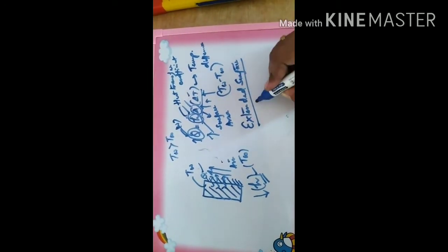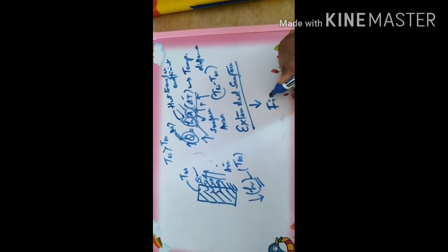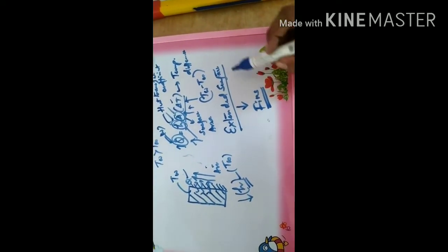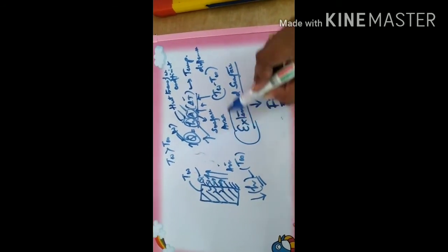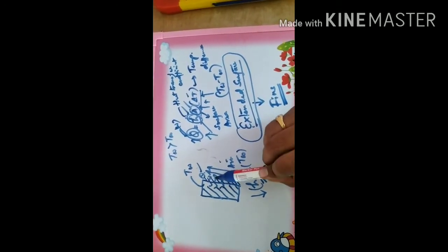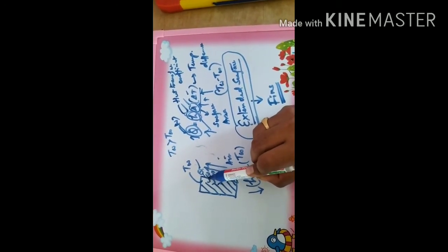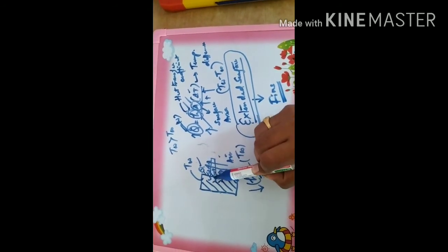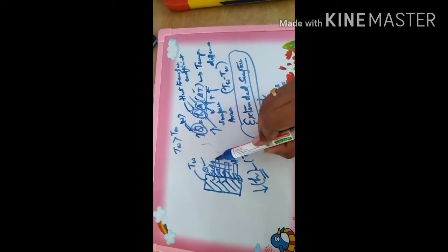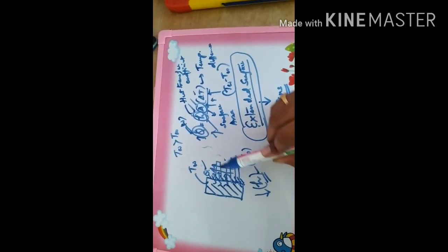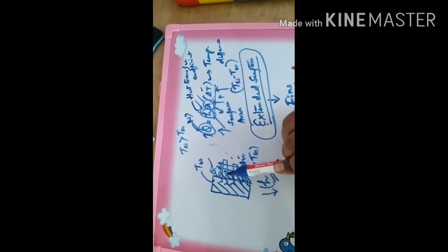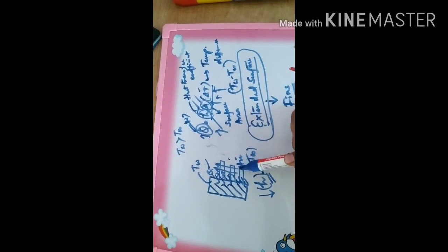These extended surfaces are nothing but what are called fins. Now I hope you got the idea of what topic we are trying to understand here. These are the extended surfaces that we are going to attach to the base surface like this, such that the area available for convection with reference to the base surface gets increased.